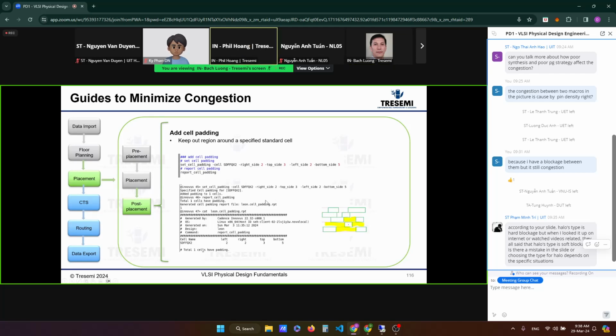Okay. So I want to add to that. This is one of the examples where we need to help the tool, the same way as the corner blockages on the macros, right? By default, the tools want to minimize the distance between cells. So if there are high speed requirements, they will place the cells very close together to minimize the RC, and therefore speed up the circuitry.